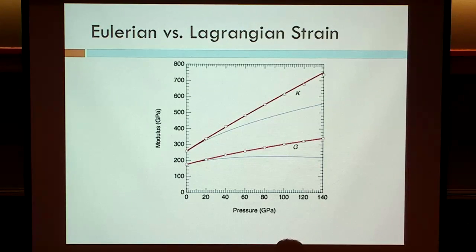Lars, is there a simple explanation why? No, there's no simple explanation why. The Lagrangian strain tends towards half for infinite compression, though? There are funny limits at infinite compression, no matter which finite strain tensor you choose. You can also choose this logarithmic strain, which also doesn't do nearly as well as the Eulerian. I think it tends to be in between these two, sort of halfway in between these two.